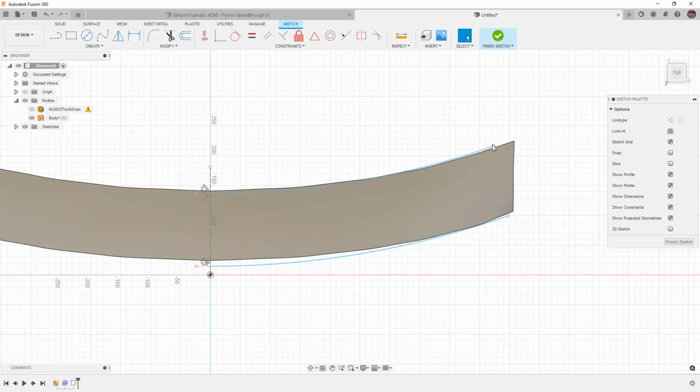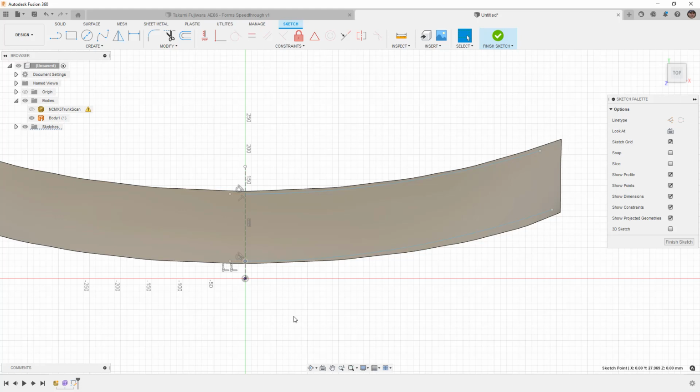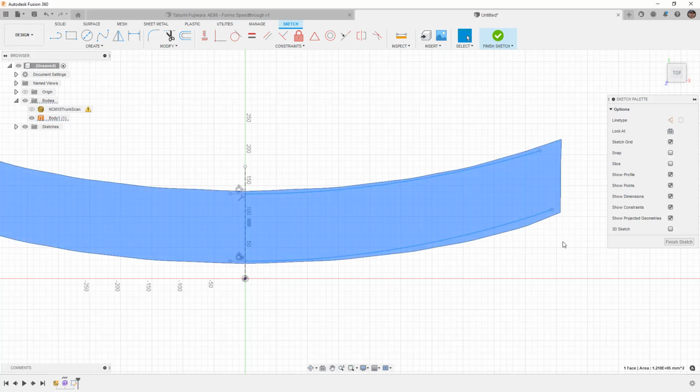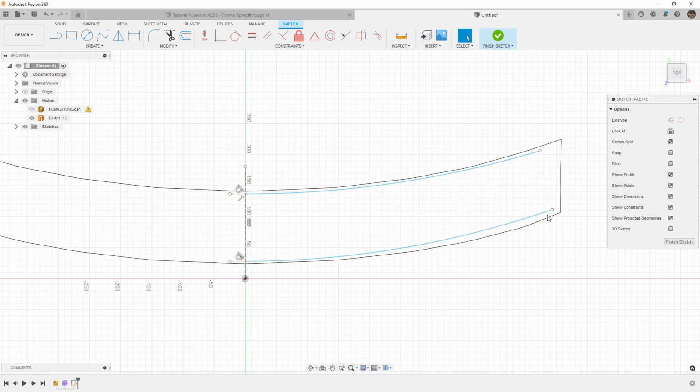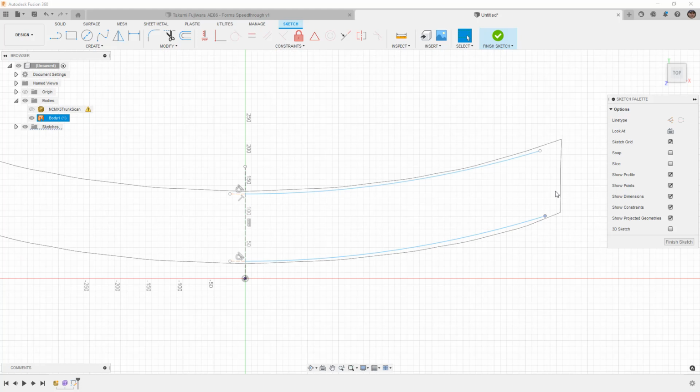I'm going to select it and just delete it because I want these arcs to be inside of my surface. So I need to make sure I pull this up. And if you have trouble seeing this, oftentimes it can be hard if you've got a gray body and you've got these light blue lines. You can always go into a different visual style. So for example, wireframe will allow you to see just the border of that profile. And now we can see these arcs a little bit better. If we're concerned with the shape, we can always bring back the mesh as well. Keep in mind that it's a little tricky displaying all of these edges and these vertices, but you can kind of see that we're trying to follow the line of the trunk. It's going to get us pretty close, so I'm happy with that.